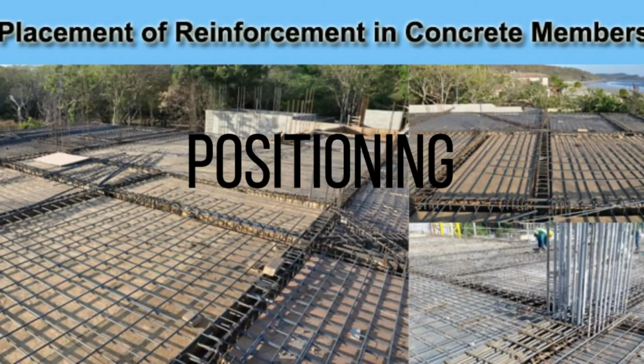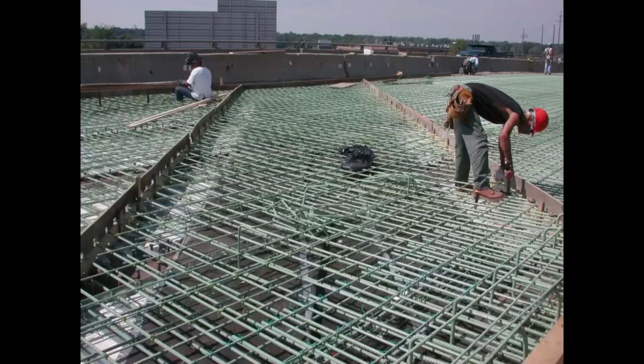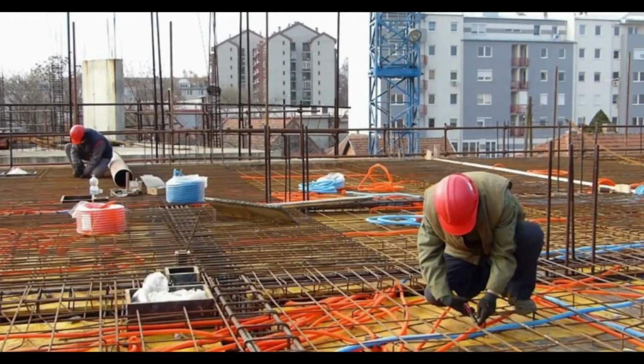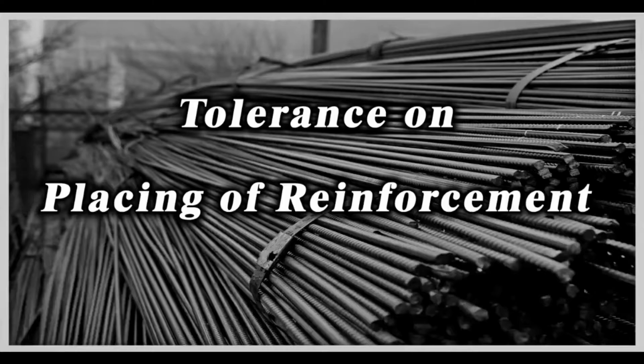Positioning. Placing reinforcement atop a layer of fresh concrete and then pouring more on top is not an acceptable method for positioning. You must use reinforcing bar supports, which are made of steel wire, precast concrete, or plastic. Chairs and supports are available in various heights to support specific reinforcing bar sizes and positions. In general, plastic accessories are less expensive than metal supports.